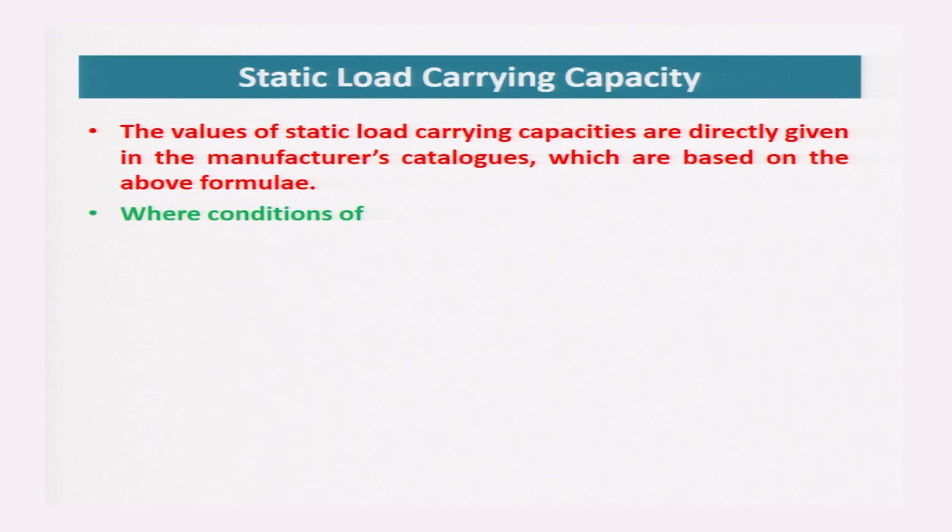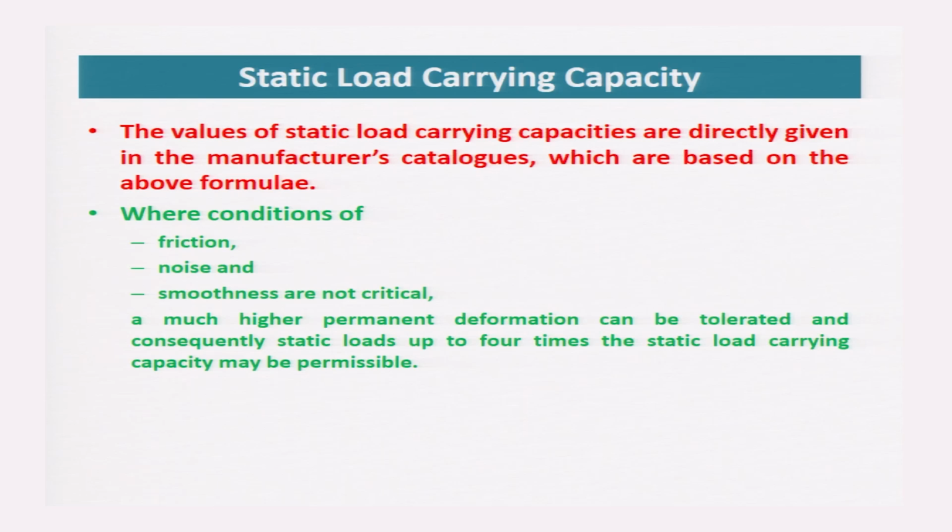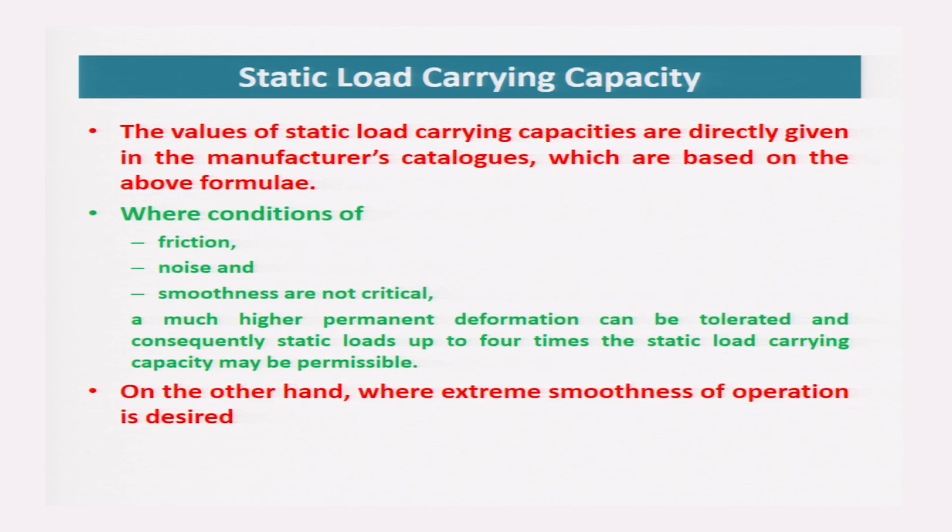where conditions of friction, noise, smoothness are not critical, a much higher permanent deformation can be tolerated, and consequently static loads up to 4 times the static load carrying capacity may be permissible. On the other hand, where extreme smoothness of operation is desired, a smaller permanent deformation is permitted.